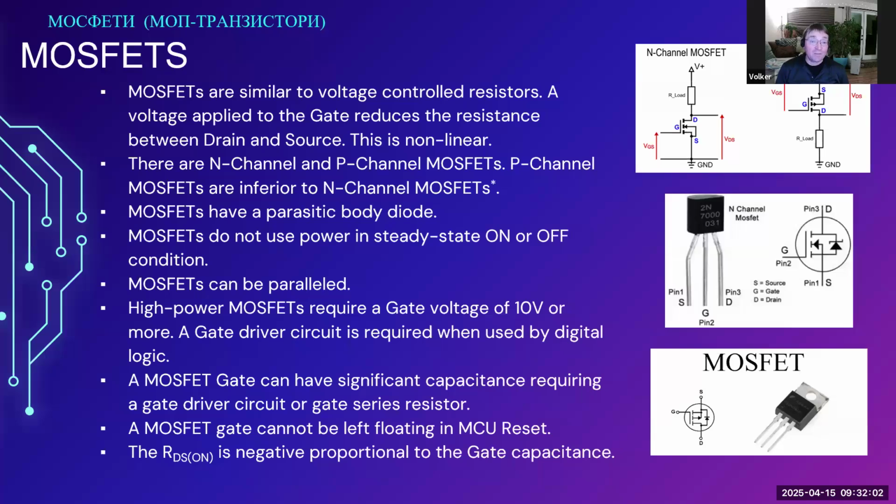In many cases, this is being done for low power bridges. But you will find just as many times that designers will go through many circuit tricks to make it possible to use N-channel MOSFETs on both sides of the bridge. So when I'm saying P-channel MOSFETs are inferior, you can find perfectly matched P and N-channel MOSFETs for use in a bridge. But generally, again, N-channel MOSFETs do have an advantage somewhere in your grouping of parameters.